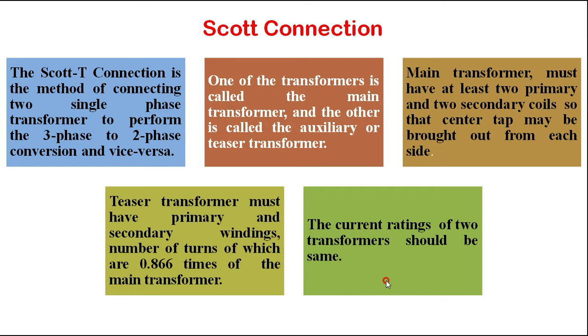The current ratings of the two transformers should be the same. Even though the tapping on the primary of the teaser side is 0.866, the current rating of both transformers must be the same.